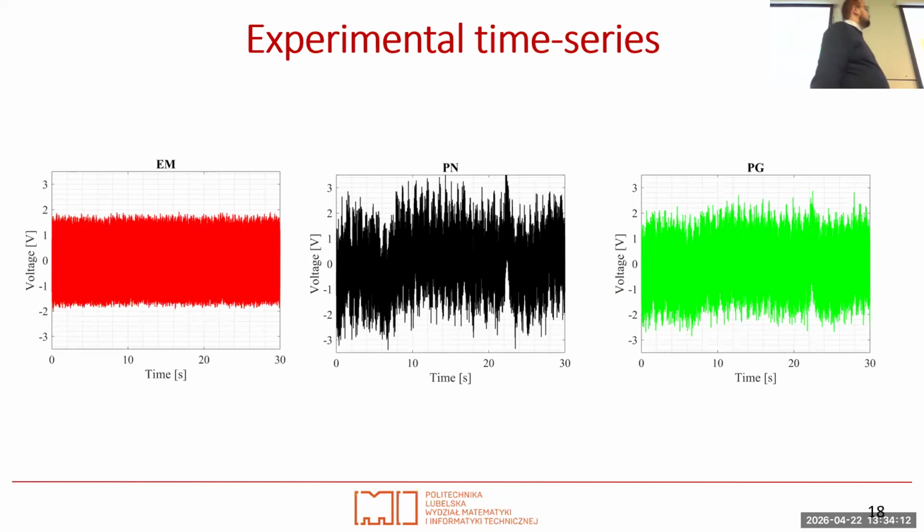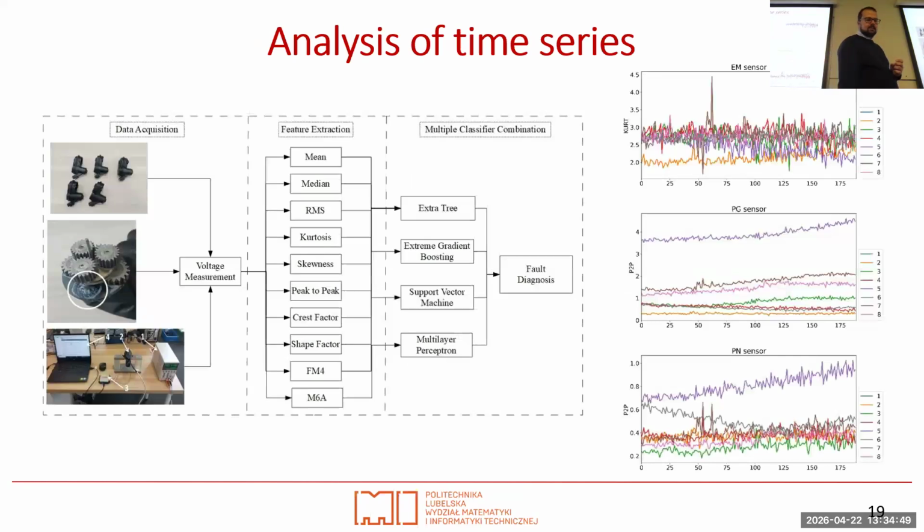For some companies, and as what we have recorded here, it was like diagnostics. Those are the output signals from the placements where we have mounted the piezoelectric sensors, like on the electric motor, on the pinion, and the planetary gearbox. From this perspective, you will not see anything. This is just the signal in time, what happens in the time domain. But as I mentioned, there is the calculation of some features. This is what has been done.